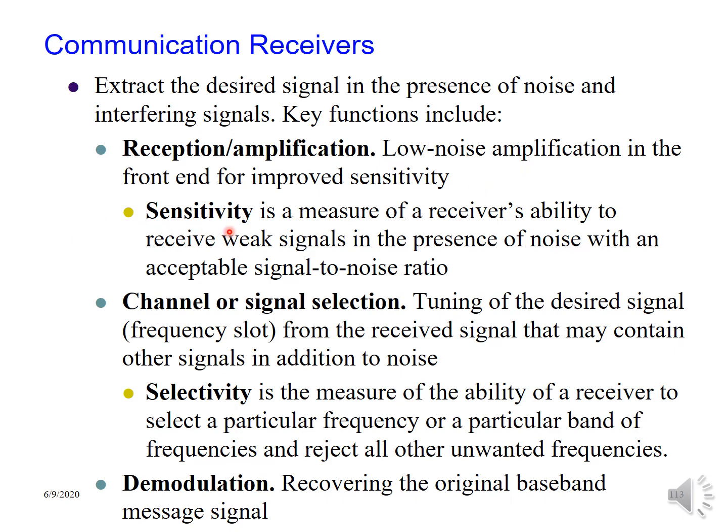So what is sensitivity? It is a measure of the receiver's ability, that means the receiving station, to receive weak signals. Sometimes the signal has traveled very far, or the transmitter power is very low, so the receiver has to be sensitive enough to amplify this weak signal, even as noise is present, but at an acceptable signal to noise ratio, meaning the signal is very high compared to noise.